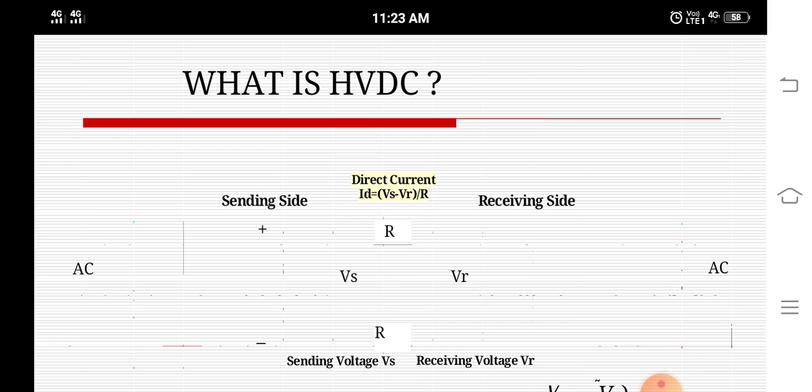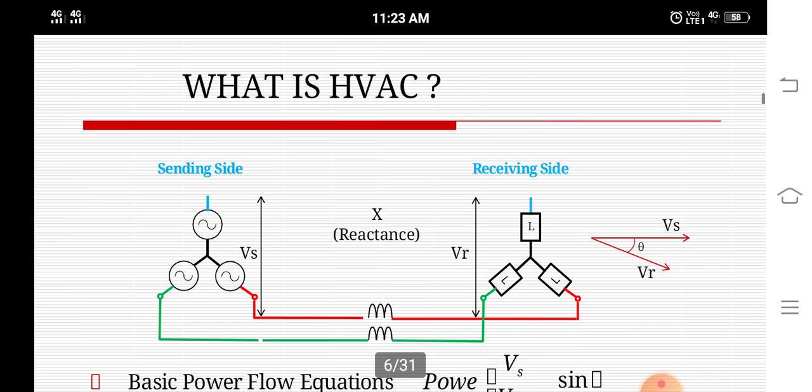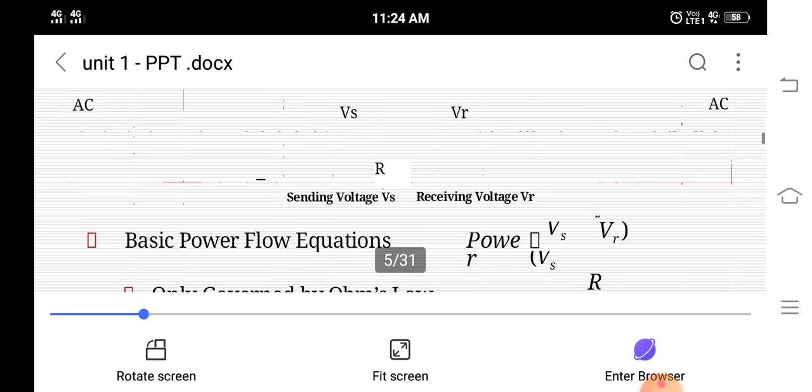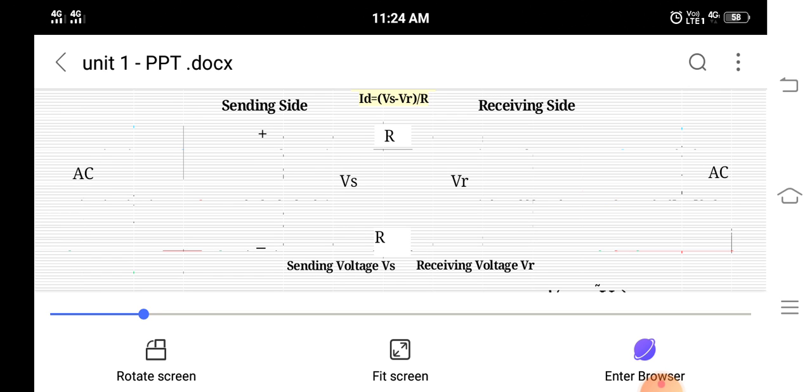But AC tends to be more economical than DC for a distance less than the break even distance and costlier for longer distances. The break even distance can vary from 500 to 800 km in overhead lines depending on the per unit line cost. Technical performance of DC: DC transmission has some positive features which are lacking in AC transmission.